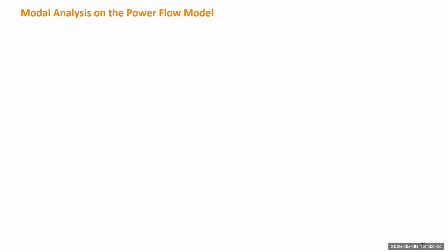Any questions? Okay, so from these slides, we're going to generalize the measures based on the PV curve and VQ curve to a bigger system. We talk about the modal analysis. Modal analysis has been introduced in the small signal stability section when we studied the oscillation damping for the dynamics of the generator. But here we can use a similar measure, but the modal analysis will be conducted on the power flow model, not the dynamic model.